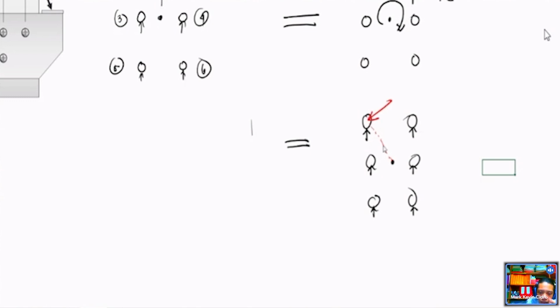Kasi in reality, whatever the distance niya nga relate centroid is perpendicular to this distance. Nakita niyo, ini nga force is perpendicular to the distance between the bolt 1 and the centroid. But since perpendicular man hiya, the orientation niya is diagonal in respect to the x and y axis. So may niya sinisiring nga x component and y component. That's why instead of expressing it as this one, we express it as its components. May niya nasugad didi, tapos may niya downward.